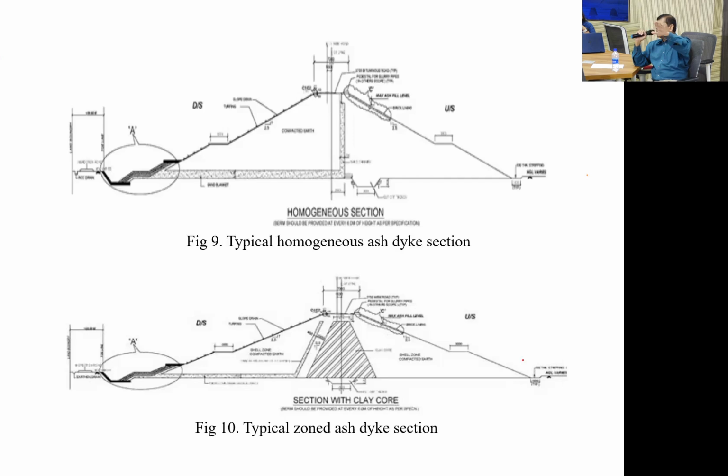But again, you are anchoring in one place, and in the other places it is fully loose. There is nothing to put into the ground. In the other places, normally we do not anchor it, but we make sure it is firm on the ground, attached to the ground, not loose with a gap between the liner and the soil. So providing that U-hook is not a very good solution. Which one? At the slope, to anchor the liner with the soil, putting the U-hook. On the slope, yes, not the crest, at the slope.